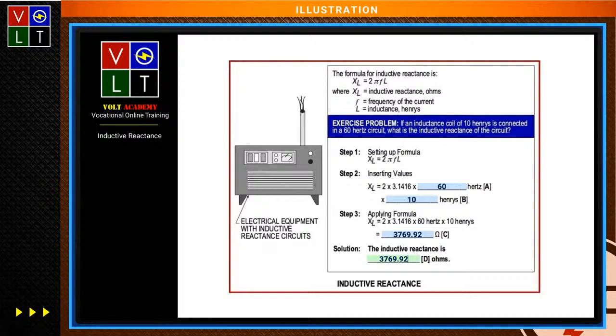Yep. And that actually comes into overcurrent ratings, where they're trying to interrupt it at half a cycle, or, when you're using the up, over, and down method, then you can actually code-compliantly interrupt it at like a full cycle, but all your selected coordination has to match. That's right. It has to be a tested pair. If you don't have that all matched, then you can't use the up, over, and down method.